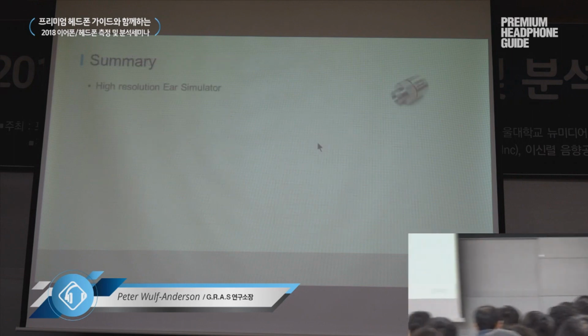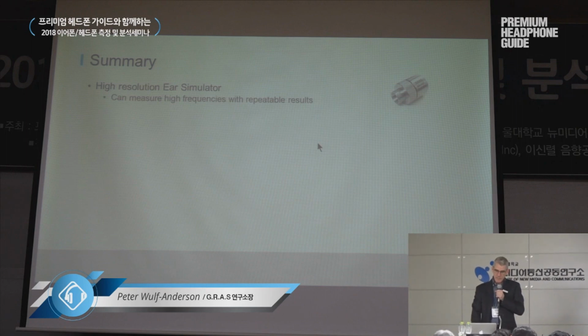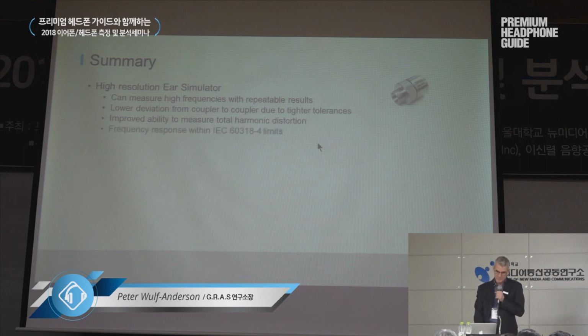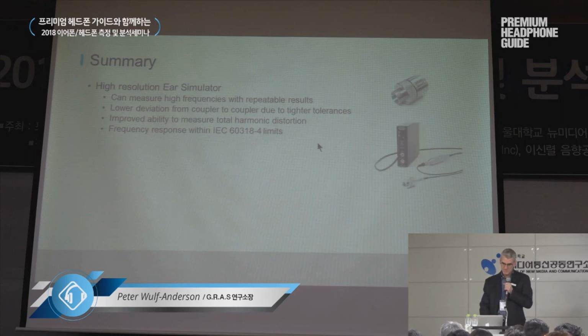So just a quick summary of my whole presentation. The high resolution ear simulator can measure high frequencies with repeatable results and much lower deviation from coupler to coupler due to the tolerances being extended. We also got the improved ability to measure THD. And we managed to keep the frequency response within the 318-4 limits or the 711 coupler limits.